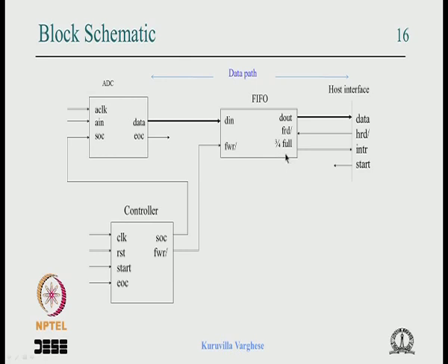So let us assume when an interrupt comes, the host will come and read less than or equal to 75%, but a fixed amount, like it will read 75% or it reads 70%, does not matter, okay. So it will read somewhere around less than 75% every time, the fixed amount. And anyway, there will be something remaining, which gets pushed when the new data comes, again it gets filled and the host comes and reads the 75%, okay.